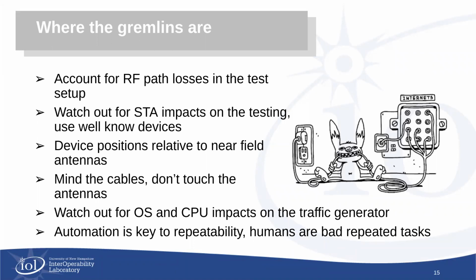Now, TR398, I didn't get into it in a previous slide, but it does outline specifically what would be that RF base case, which is essentially trying to get to about a 2 meter free space loss, right? So if it was implemented in the ideal world, you would have the station 2 meters of open, clean air away, and then the device under test.